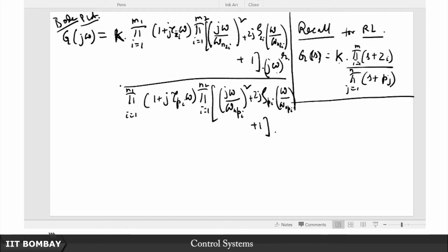On the other hand, here if you wanted to find the DC gain, it would basically be this k. So the DC gain would be equal to k times the product of zi upon the product of pj, right. So this k and this k are definitely not the same; we are setting it up in a different fashion. Please be mindful of this. Every single tool that you use has some typical nuances, some typical ways of dealing with it.